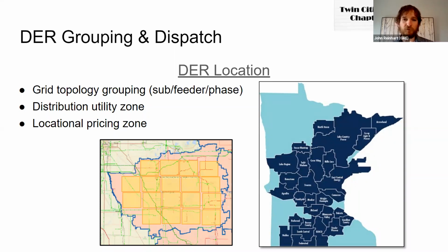The different zones or the different cooperative zones, in our case, it's important to be able to isolate and send in unique instructions for each of those. But also for pricing zones, this goes back to the wholesale price perspective that costs can fluctuate based on the locational price. And it's good to be able to move those in concert, one up, one down, to respond to those prices, in addition to generation profiles from wind and solar.